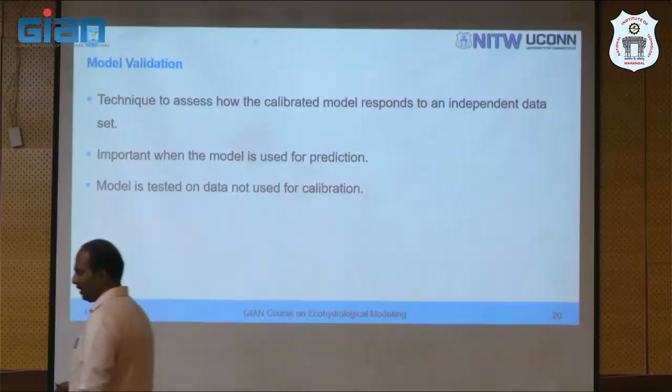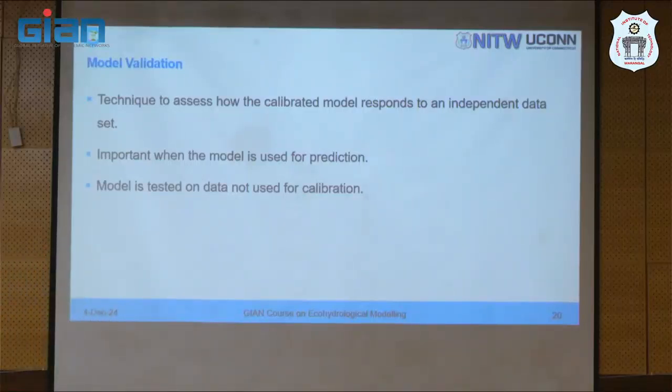You got a 0.95 NSE, and then in your validation, let's say you got only 0.1, 0.2, or sometimes even negative. That means your model is not even suitable during this period. It cannot be applied. That means any predictions that you make with that particular model are not valid for any period other than 1990 to 2010.